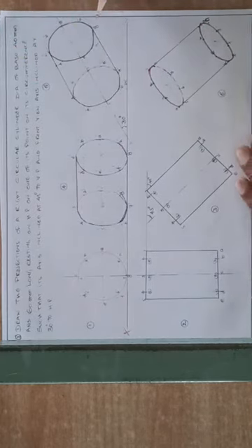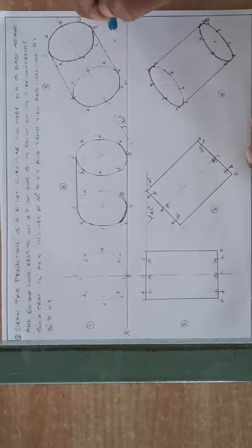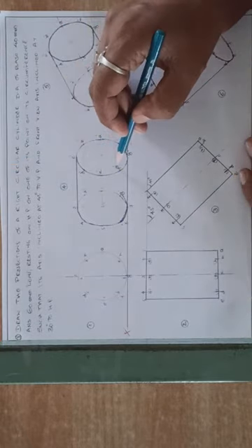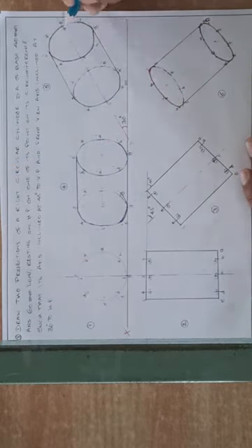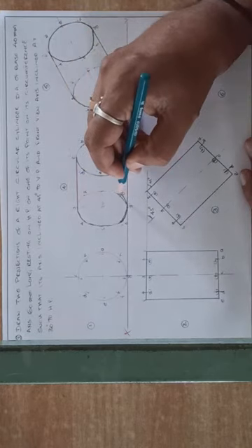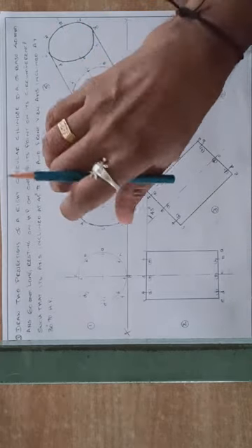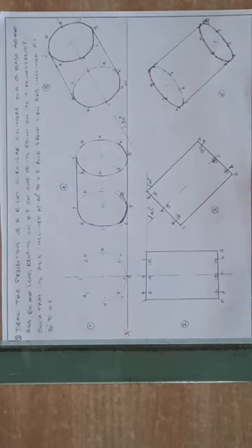Draw the horizontal lines. Here you are getting the points. The same figure you are transferring. Here this face is visible, here also make this face visible. Here the second half face is dotted, here also the second half face is dotted. Same object, same position, transferring it.